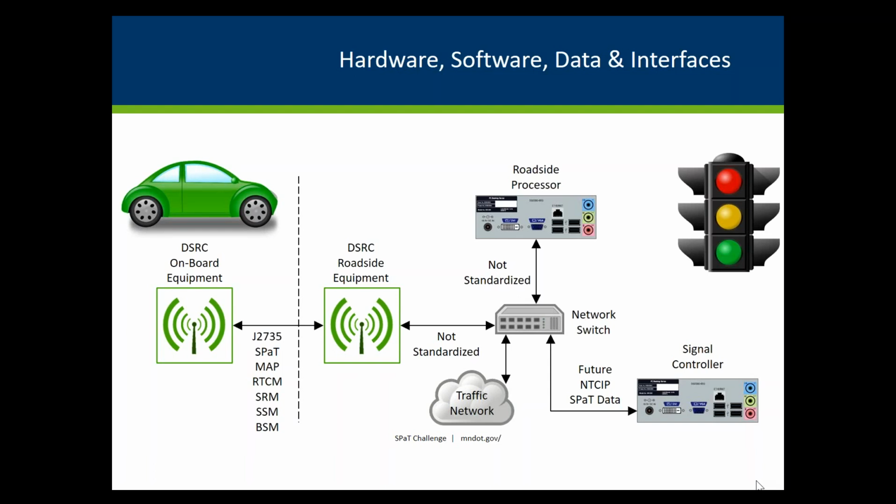So between the traffic signal controller and the DSRC, there really aren't standards as to how that works. And everybody makes their DSRCs a little different. Some of them, you can write your own software and run it on there using some of their software libraries. But then you're stuck with their brand because that's not a standard. It won't work on somebody else's. So that was one thing I wanted to point out.